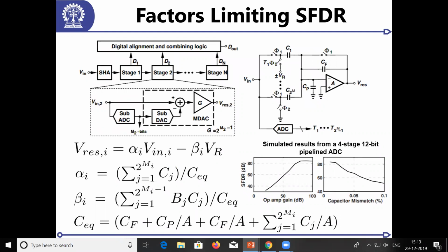This kind of dithering is called deterministic self-subtractive dither. Deterministic because I know exactly what I'm adding. Self-subtractive because if I average all of them, it is 0, so it is automatically subtracted. I don't have to do anything special at the output. And dither is a very common technique used in almost all systems.